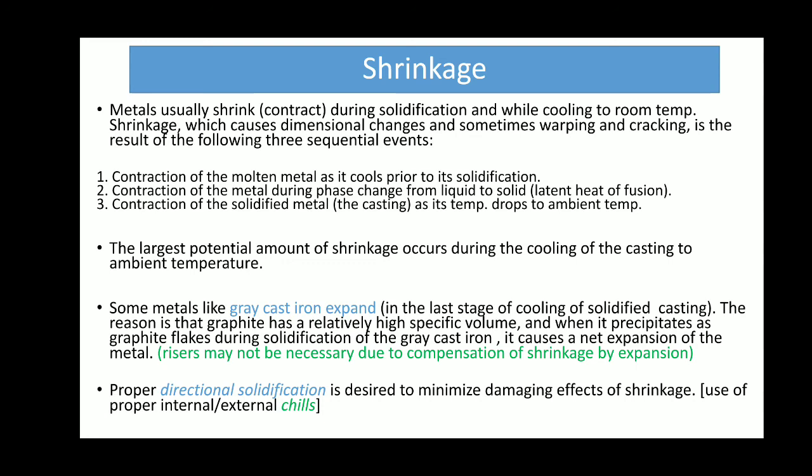So it compensates the contraction that we already had and nullifies it. Because of that, sometimes risers may not be necessary in casting with gray cast iron. This is sometimes asked in competitive exams. We also know we want directional solidification, which is desired to minimize the damaging effects of shrinkage, and for that we use internal or external chills, etc.